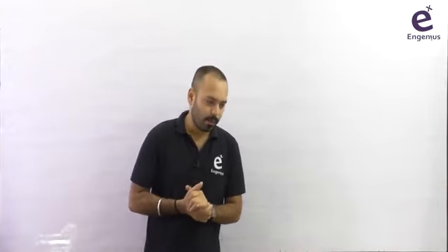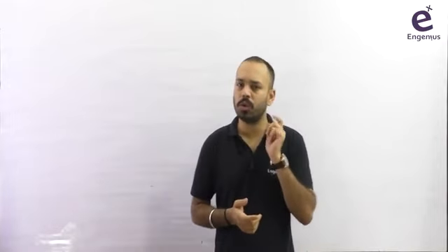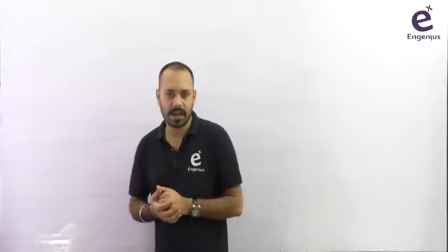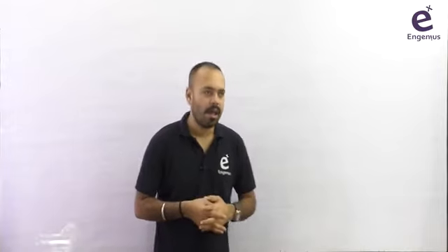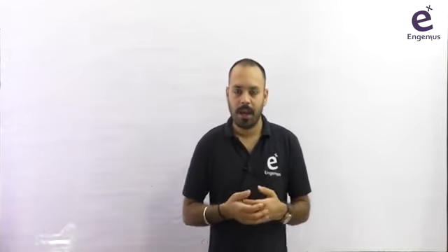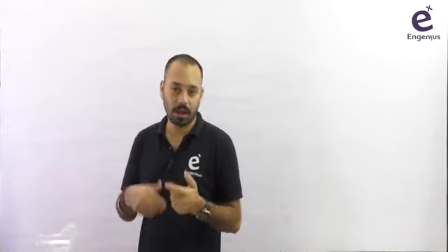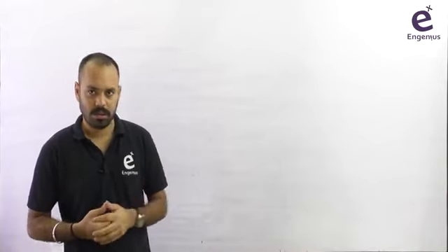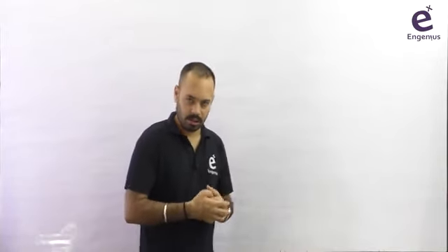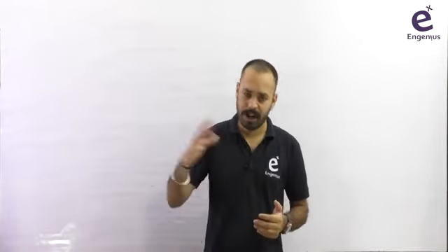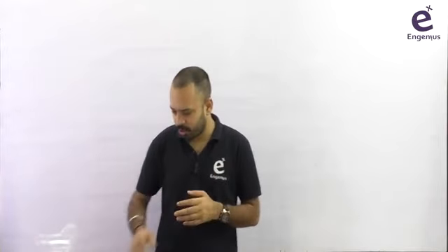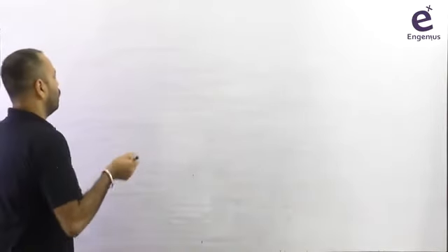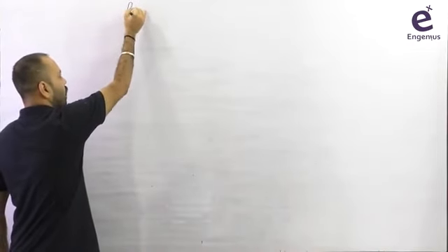The first thing that I'm going to discuss, you remember I asked you two questions. In which case can a CSTR act like a PFR? I already answered that when you combine a number of CSTRs in series and when n tends to infinity, it practically behaves like an ideal PFR. The other question can also be asked in the reverse manner: in which case can a PFR behave like a CSTR? So in today's class I'm going to answer that question. The topic we are going to discuss here is the recycling in reactors.